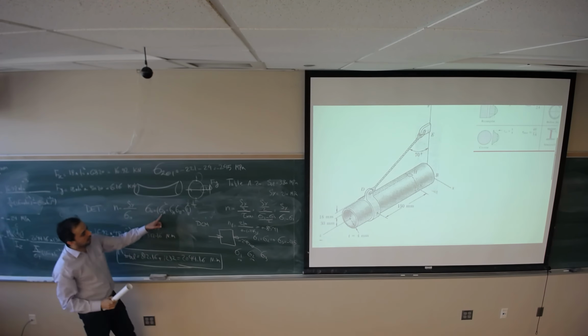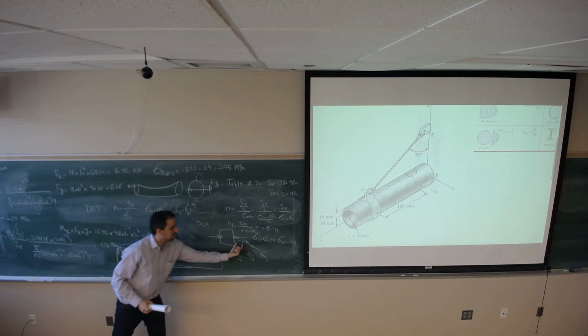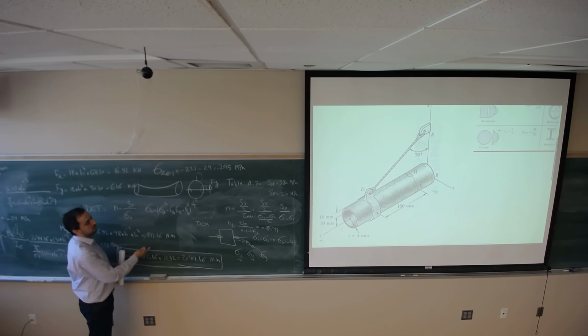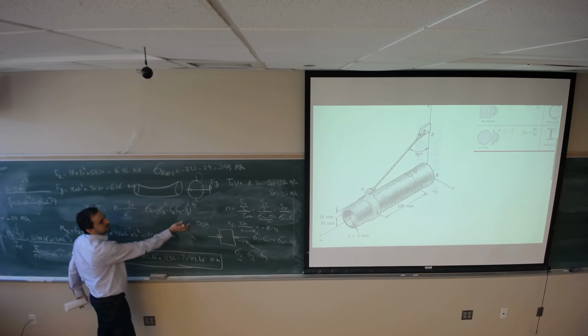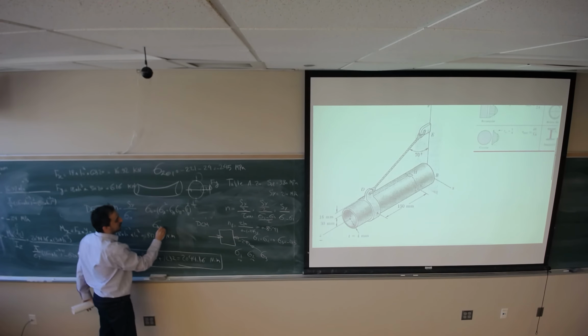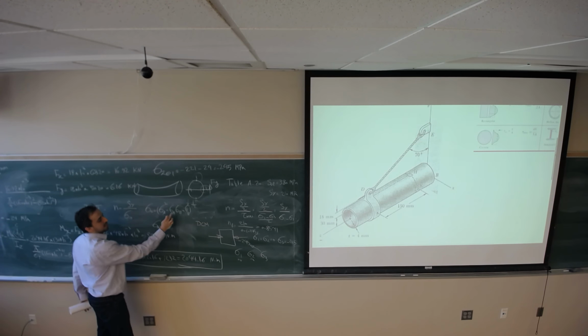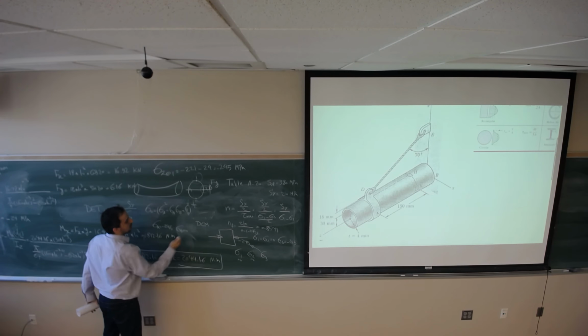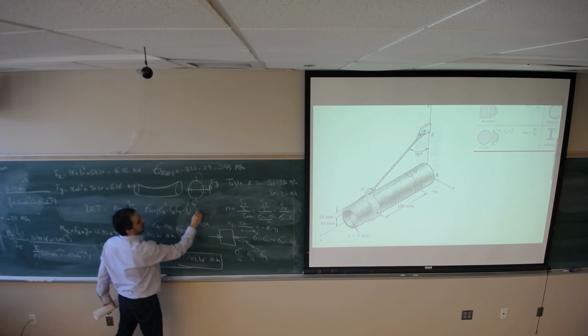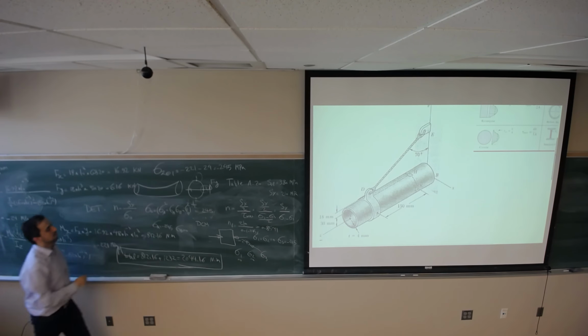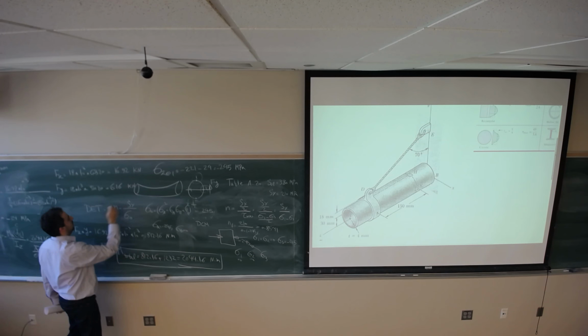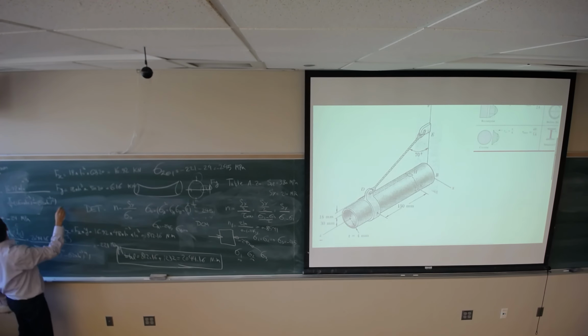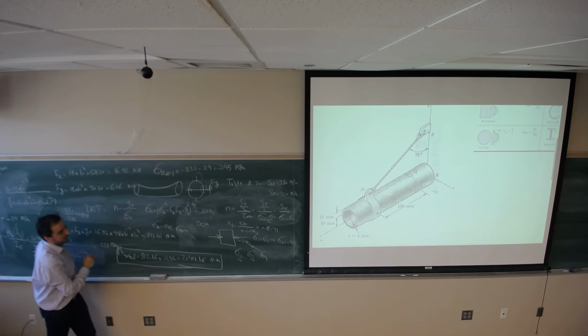Now, sigma A can be negative 245 or sigma B can be negative 245. In any case, the other one is going to be 0. Suppose sigma A is negative 245, this term and this term are going to be 0 because sigma B is 0. So the square root of sigma A squared is going to be 245. SY, 210 divided by 245, you will get the same thing, 0.8571.